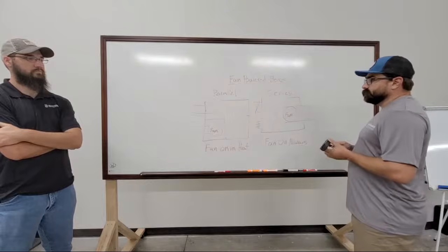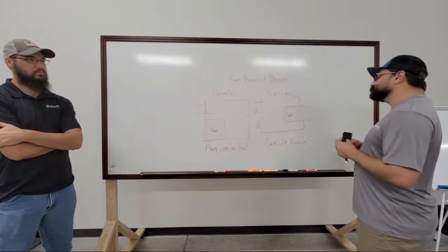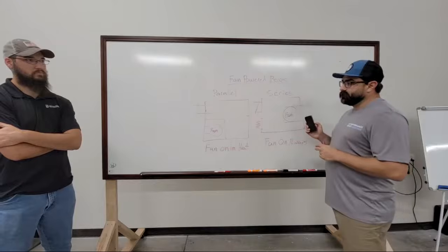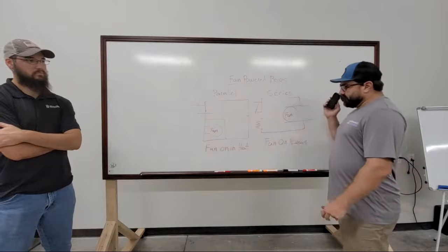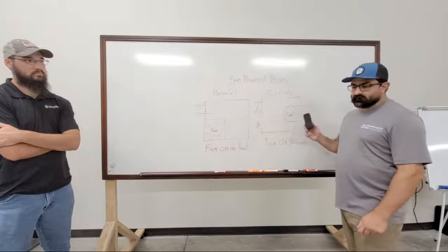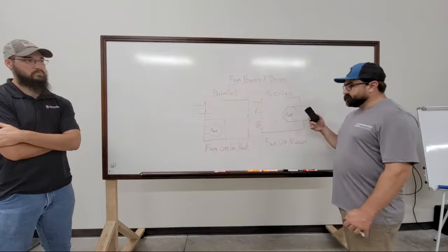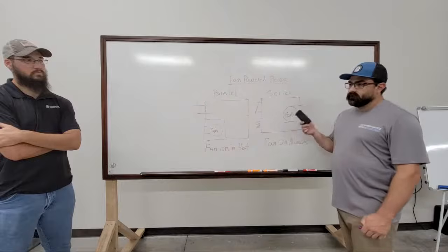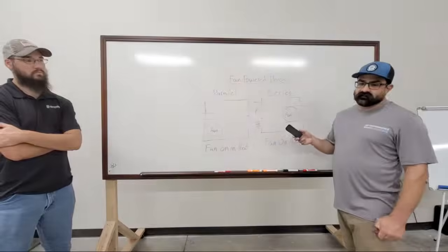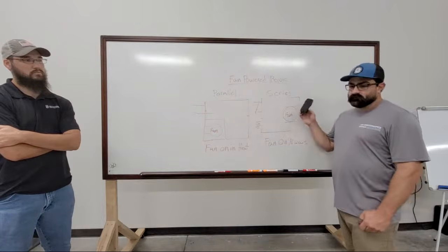Okay, the reason there are two types of boxes. I'm not super versed on this part of it because it gets more into electrical theory. But from my understanding, the idea behind a series box is that a fractional horsepower motor draws less current than your high horsepower motors in an air handler. So in theory, you can have a smaller air handler with a smaller motor when you have series boxes, because you are shedding that load from the main air handler and putting it into the box.